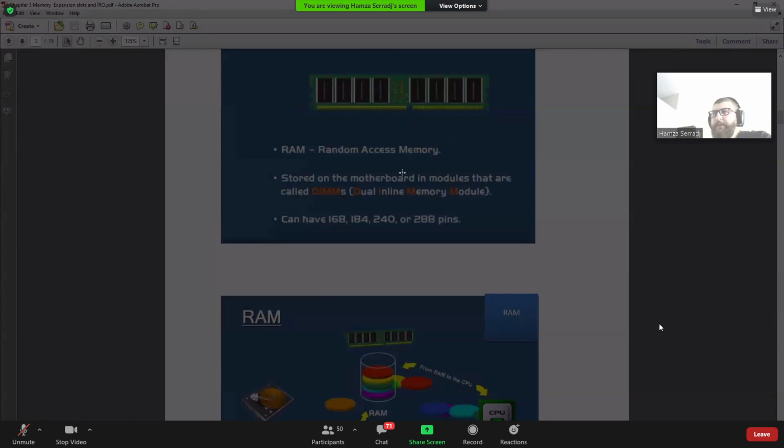SRAM does not allow a bigger amount of memory. Compared to the RAM, they are much more expensive, right? So they are in kilobytes or megabytes just for the caches of the CPU. Well, the RAM, the DRAM, is in gigabytes, the capacity. But the SRAM, the caches, are just in some kilobytes or megabytes. For the L3, some megabytes. L1 is in kilobytes.